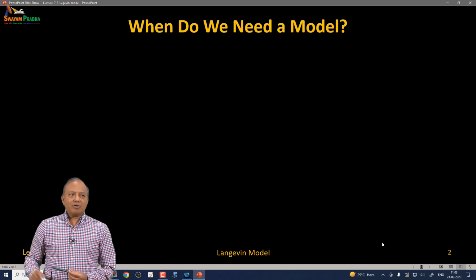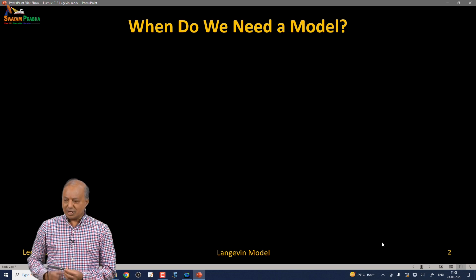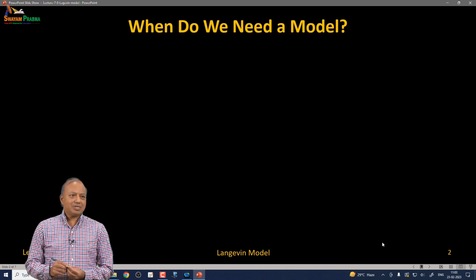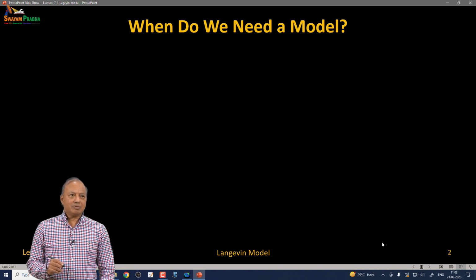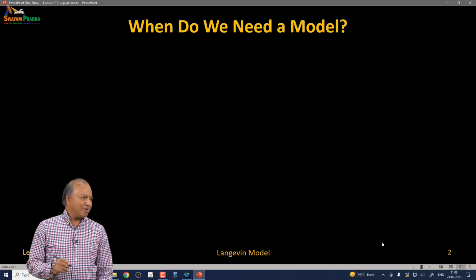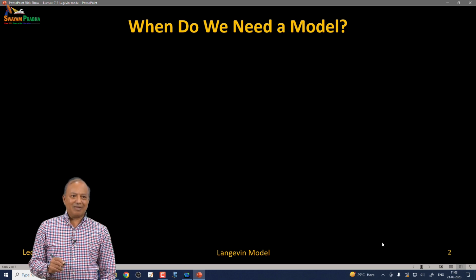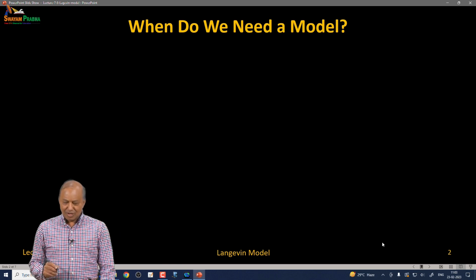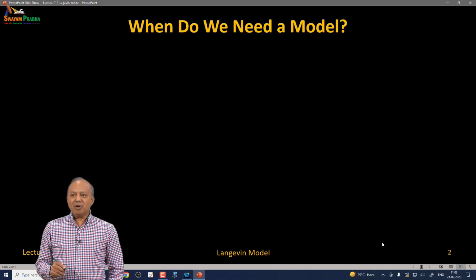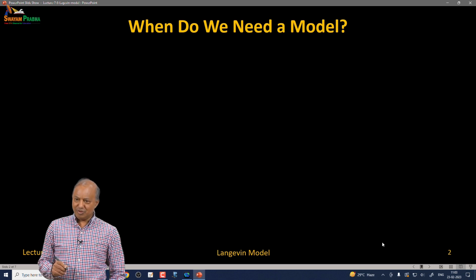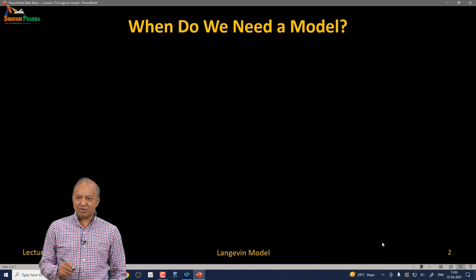Now, for this discussion, let's just talk about small particles, sort of like sub-Kolmogorov particles, to make life easy. So these are very small particles. What's the advantage of these small particles? You can use BBO equations to move them. You don't have to put a grid around the particle.